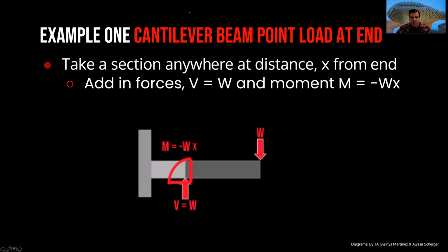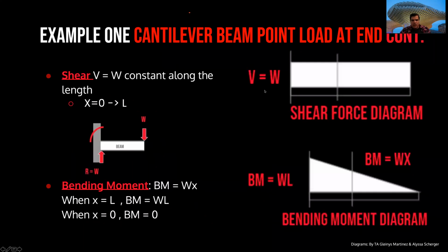Okay. Well, how you calculate these particular forces and moments is very simple. We imagine that we got the beam, as we have been doing until now. If we want to calculate the force in this particular place, and force means the two possibilities, bending and shear, we cut the beam and we look at what happens at the left, or we look at what happens at the right. And that will give us some diagrams.